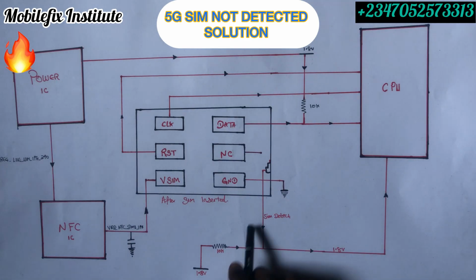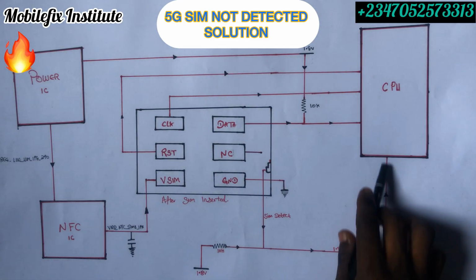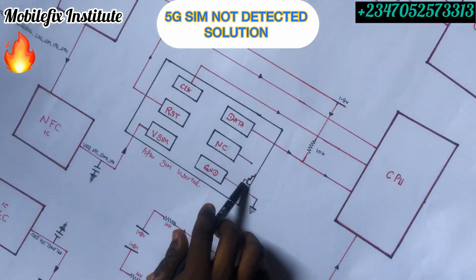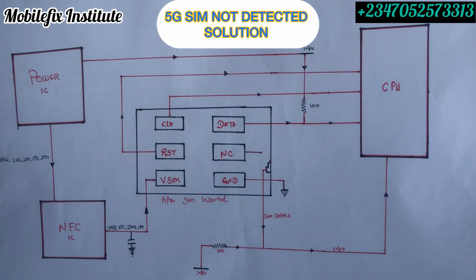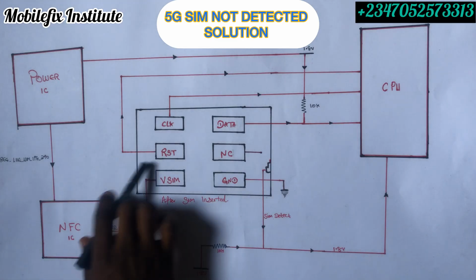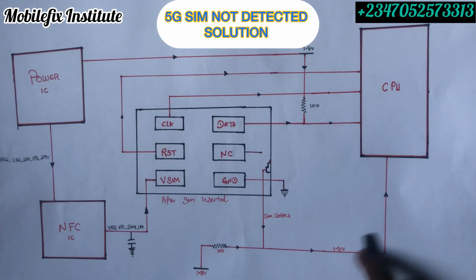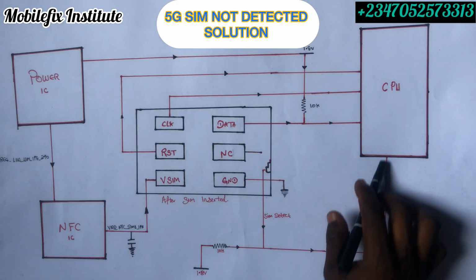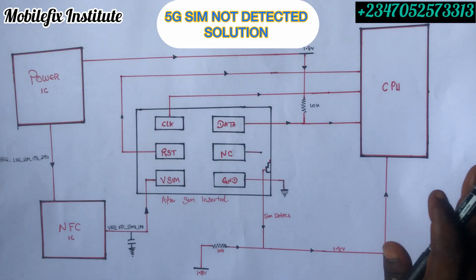Now when this line is connected to ground, when you've not inserted your SIM card tray, the CPU will not sense anything, because this whole line, from here to the CPU, is ground, since this pin is connected with the ground. It will only show that the SIM card is not inserted. Now when you insert your SIM card tray, this pin will disconnect from ground. Now this line will no longer be ground. Now this 1.8 voltage will be able to pass to the CPU. Now the CPU will sense that a SIM card has been inserted. That's how the logic works.